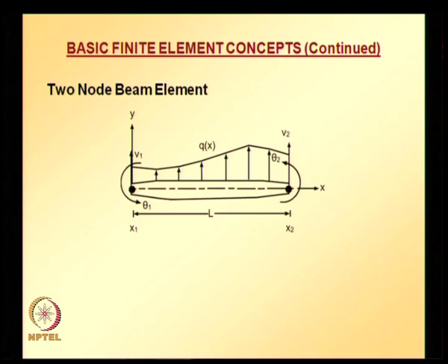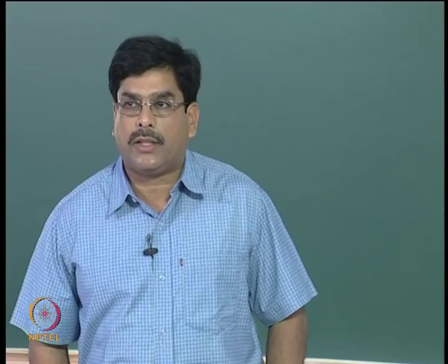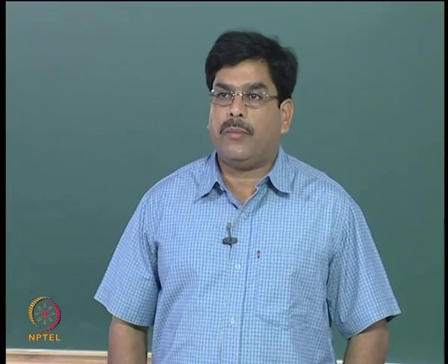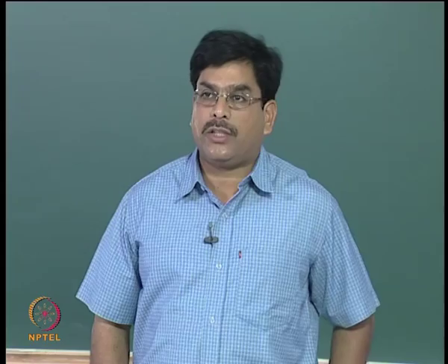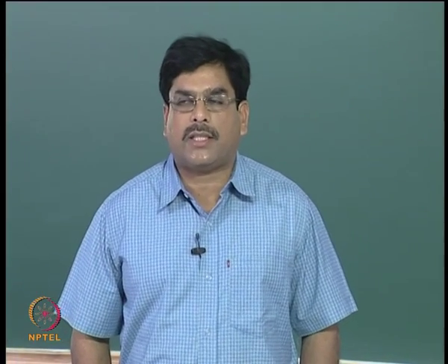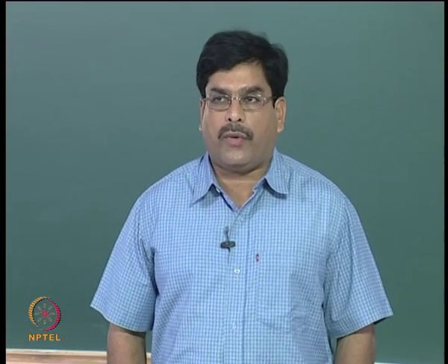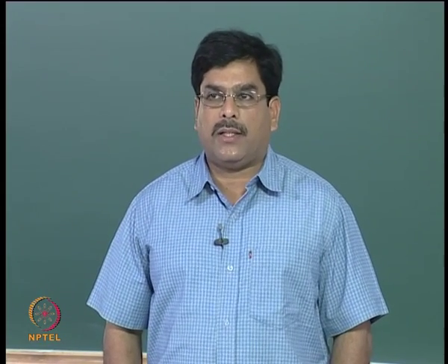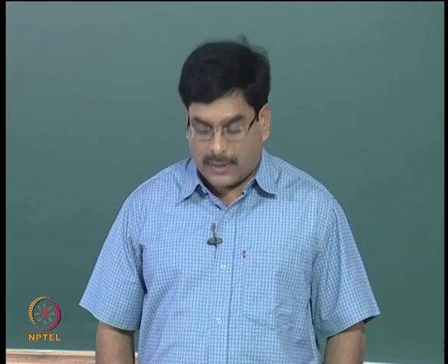and here EI is assumed to be constant over the entire length of the beam element, and the applied load along the element length is uniformly distributed. So Q is uniformly distributed and EI is assumed to be constant, and we will be using these conditions when we are trying to simplify the stiffness equation and also the load vector.